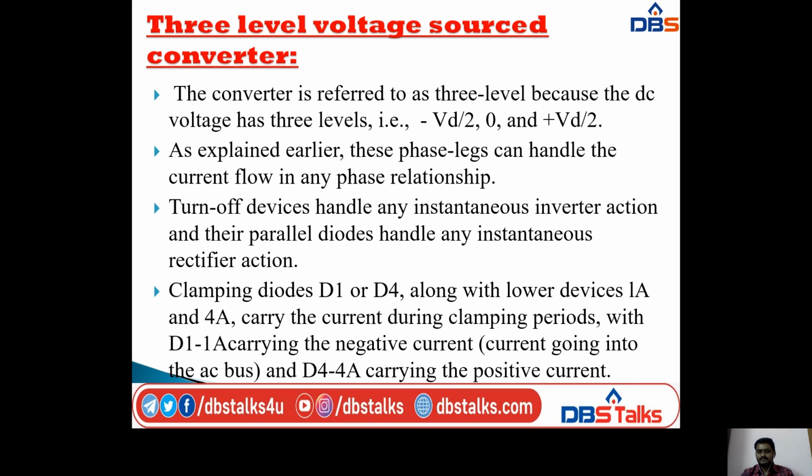Next, as explained earlier, these phase legs can handle the current flow in any phase relationship. The turn off devices, thyristors, IGBT, IGCT and the like, handle any instantaneous inverter action, and their parallel diodes handle any instantaneous rectifier action.